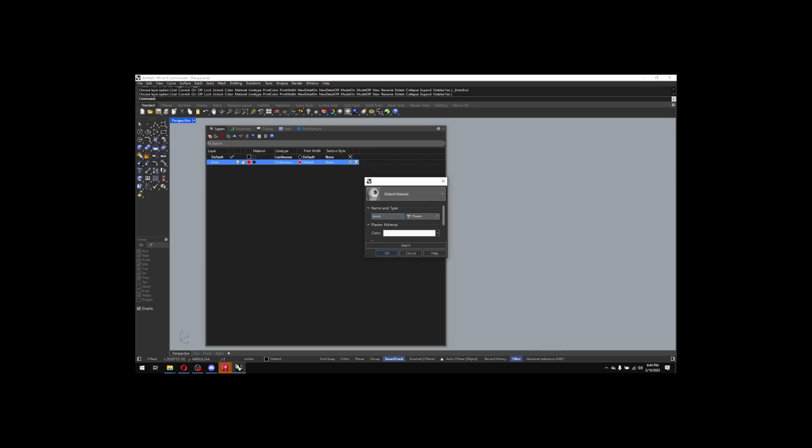If you put a space in there, Lumion will not pick up the space. So if you type in your material window brick space herringbone, it will only read brick. And if you have another material that has brick at the beginning and then a space, it'll assume that they're the same material. That got me hung up for a long time, so just avoid spaces. Underscore, fine. Basically anything there other than a space, it'll read it.